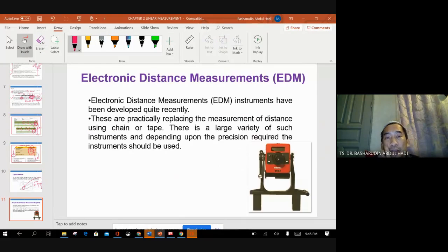Lastly, we have electronic distance measurement, and normally we put it on the theodolite. The theodolite measures angles, and the electronic distance measurement does its respective work. It is horizontal distance measurement based on radio wave or laser wave. They integrate the electronic distance measurement and the theodolite to form what we call the total station. So by the end of that, we finish chapter 1 and chapter 2.